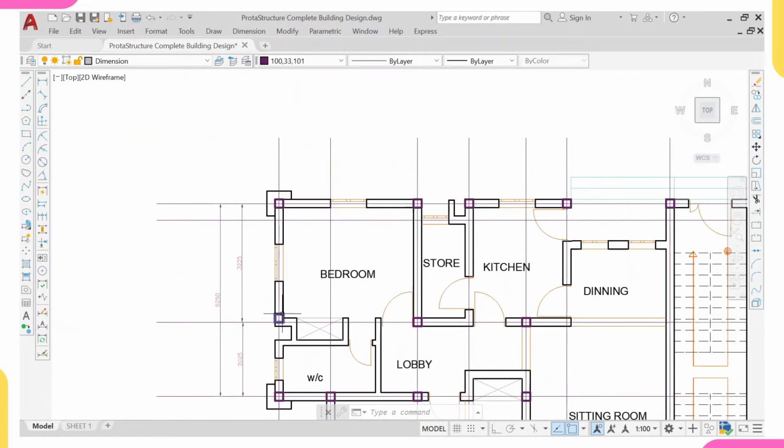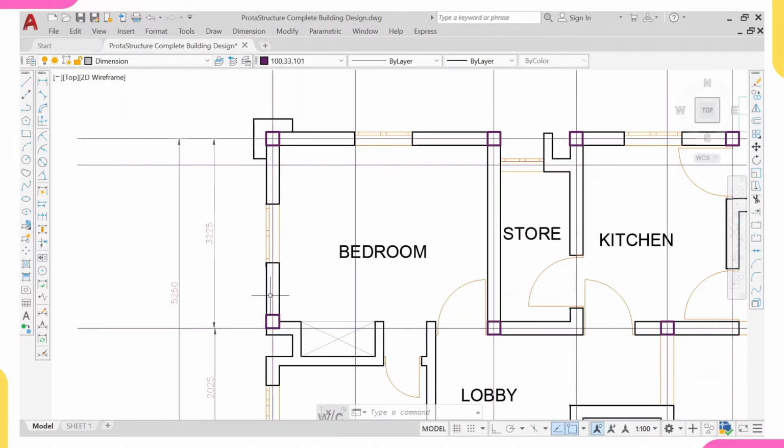You know, if he's an amateur engineer, he will place columns all around. He will place a column here, he will place a column here, and he will place a column here. And if you place a column here, let me tell you, that means this beam must surely be under 2y16, it is a must. But the thing is that it will be under 2y16, but economy is no longer in view, because if I remove this column and have 3y16, I'm still making profit.